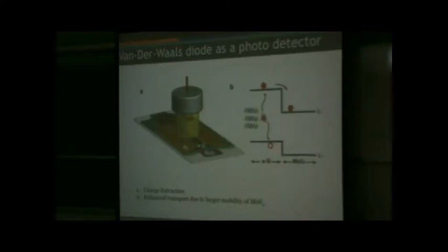The second thing we realized is that amorphous silicon has extremely low mobility, less than 1. Now MoS2, people quote mobilities from 20 to 1,000, but it is much larger than less than 1. So if I can separate a charge out into the conduction band of MoS2, this will go much faster. So my speed of the imager will become very fast.